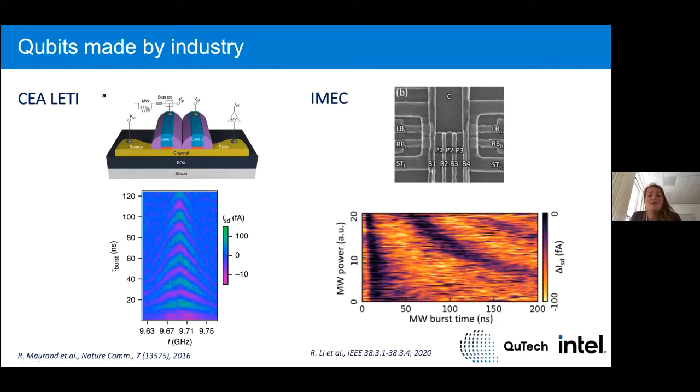And moreover, for the crucial fine gate structures that we make our qubits with, so the small gates, they still use e-beam lithography, and in some cases liftoff. These techniques offer a lot of flexibility, but they are also very slow. And moreover, there are indications that these techniques might cause damage to the material, and this results in increased charge noise, so low fidelity qubits, and therefore these techniques might be hard to scale.